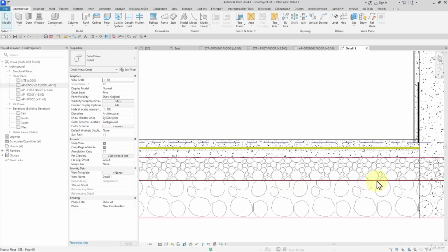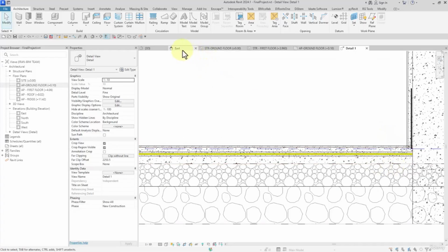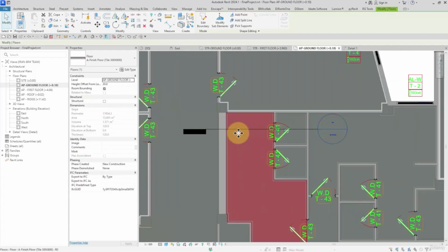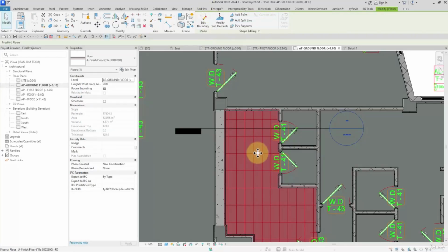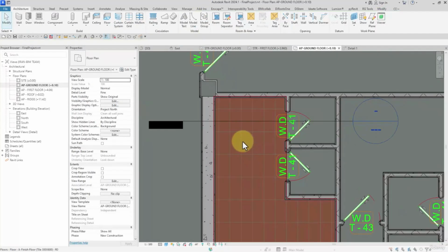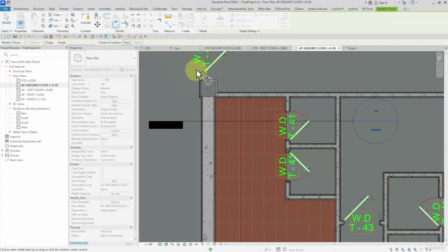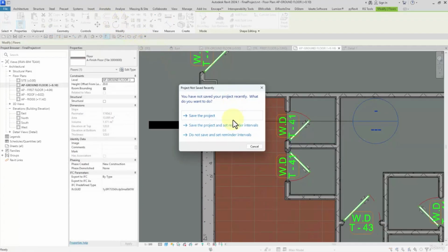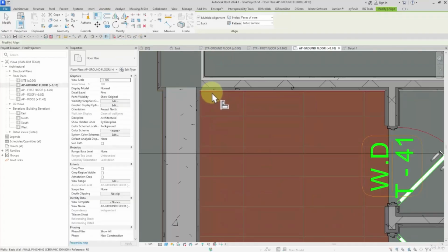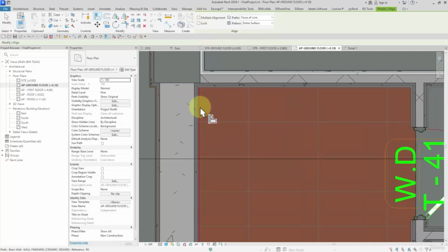Watch this to remove the warning message. Check the details, it is perfect. We get back to this part, and the direction of the flooring is different. I hold down the cursor of the mouse, then I press down Tab to select the pattern, then using Rotate to rotate it at 90 degrees. Afterwards I pick Align. I want to align the fill pattern this way, and also this finishing layer